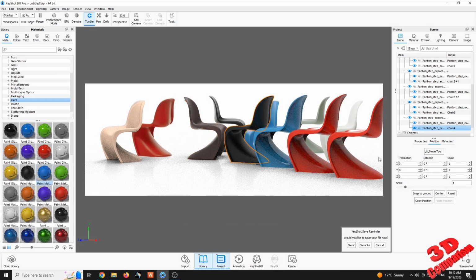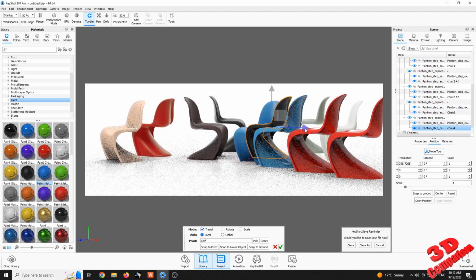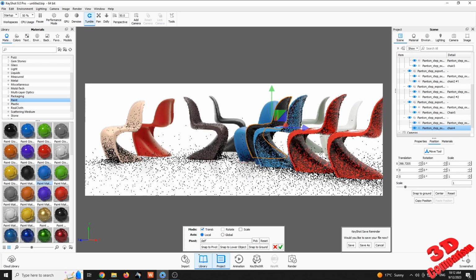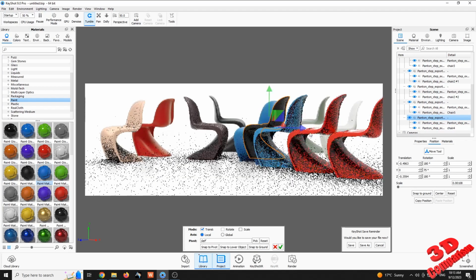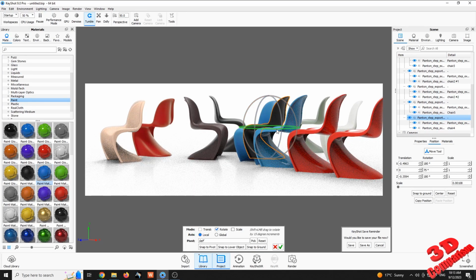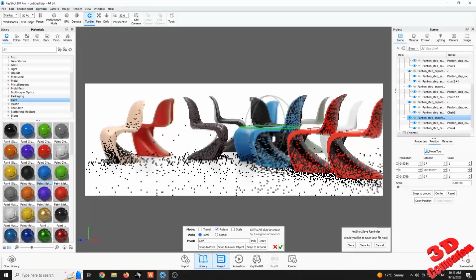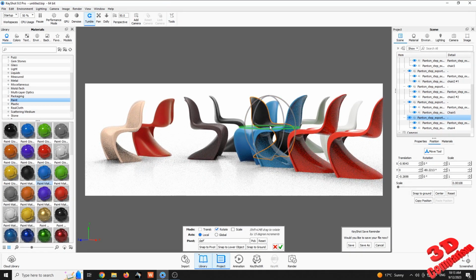We're gonna go with the following one, which will be the blue chair, the black chair. And we see, since I only selected and moved it, a sketch that was used to define that remained over there. So that's why it's important to always check for this and have that model, the large parent, move so that there won't be any leftovers.